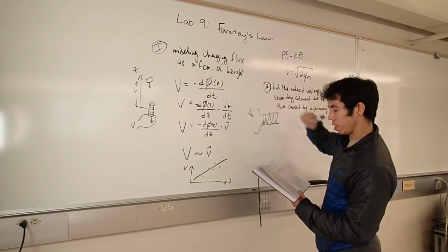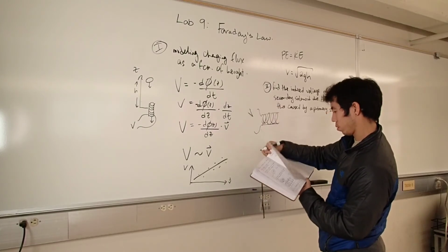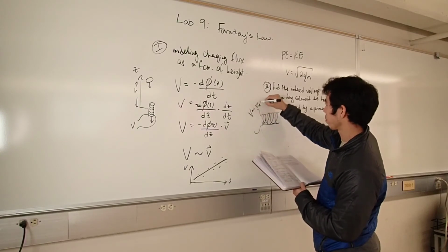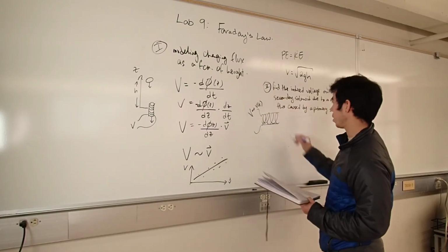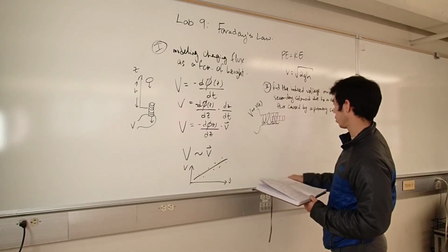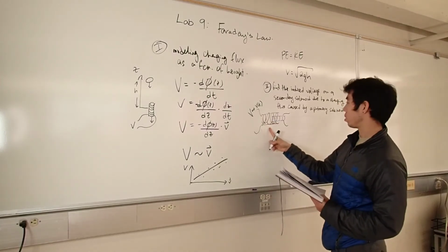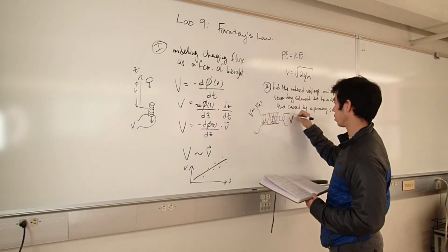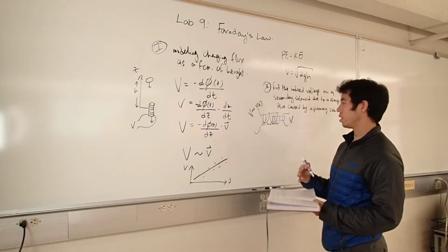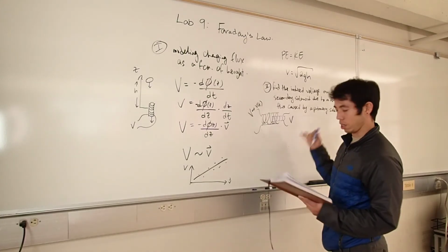The voltage on the primary solenoid will have some time dependence. And then we will have a secondary solenoid inserted into the first. The time-changing flux in the first solenoid will induce a voltage on the second solenoid. So just by virtue of being in the vicinity of the first solenoid's magnetic field, we should see a voltage on the second solenoid.